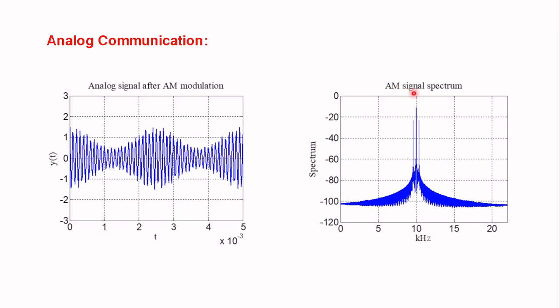Here we can see the carrier in the middle and the double sideband of our modulation. This is called amplitude modulation, or AM, which is simply modulating our input signal on the amplitude of the carrier, as we can see. And the receiver can simply receive the signal by extracting it from the amplitude.